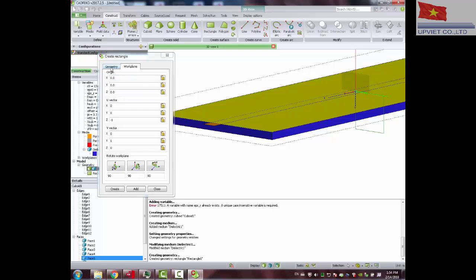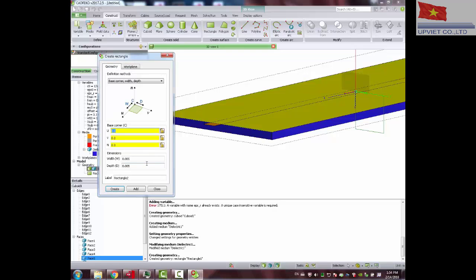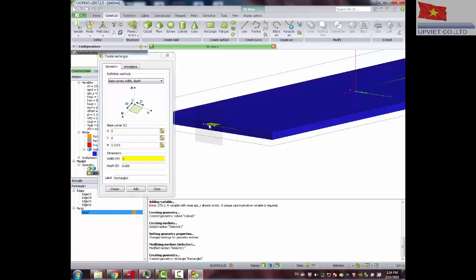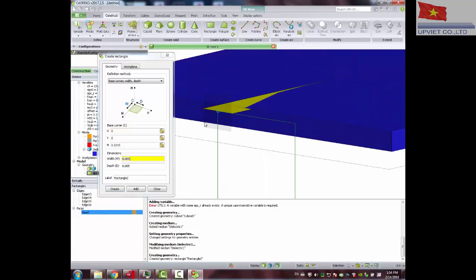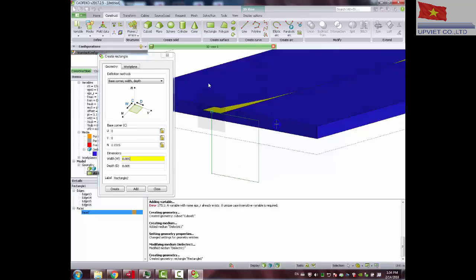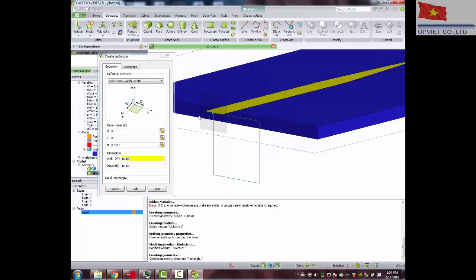So then we move to geometry, and the active area is the one highlighted in yellow. We type in Ctrl Shift, and now using this option here, we pick the middle point, as you see here. Twice, it's done. Now our plane is aligned here. You can see that this shadowed square is showing where the rectangle is going to be constructed.